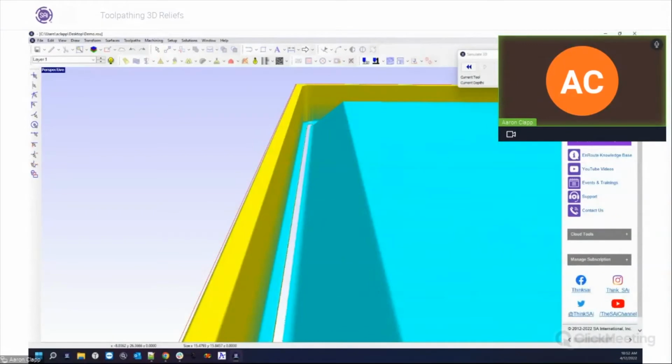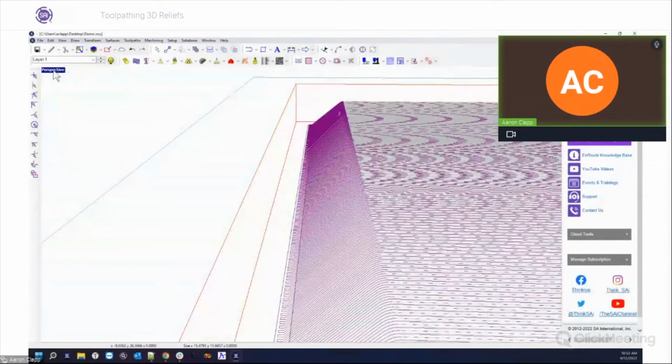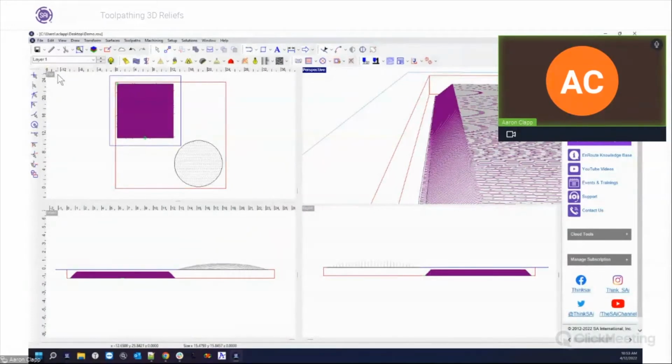For a higher quality, smoother finish, you want to go higher on the overlap settings so that you don't get that little ridged look and then have to do a bunch of sanding, especially on foam or hardwood. Hardwood specifically would be a bummer because it's a very difficult material to remove.